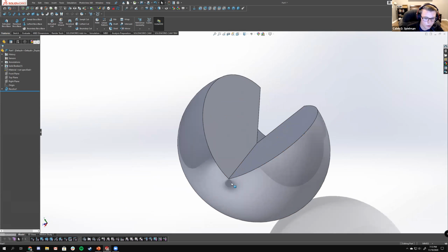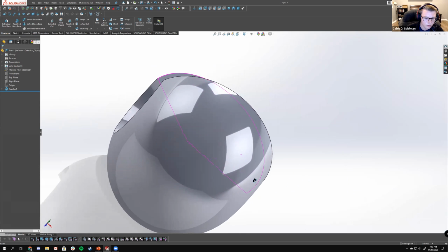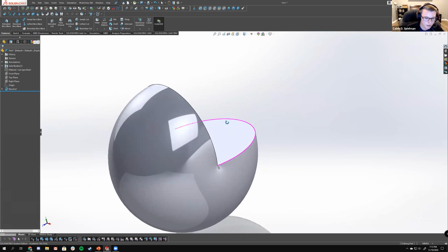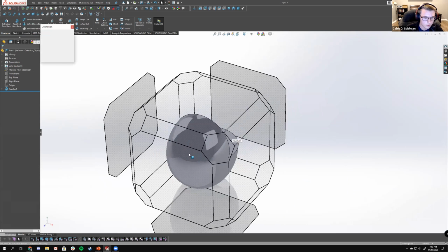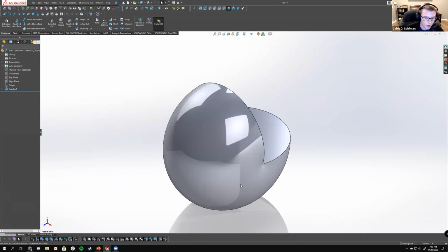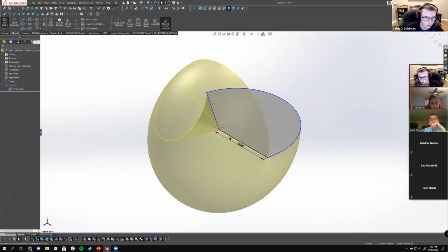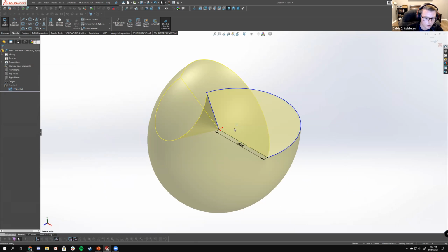It's generally the Revolve tool is very, sometimes it disobeys. It's not always consistent with how you can do it and when. So you just have to manipulate the sketch to do it as you want. For example, watch this. I'm going to make this a construction. This contour is now open.